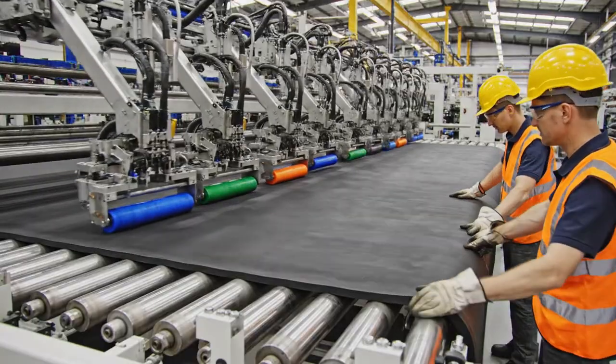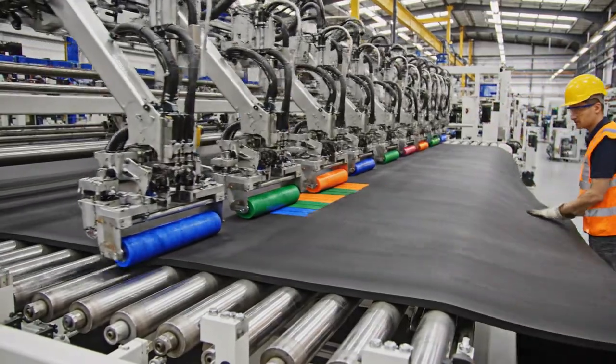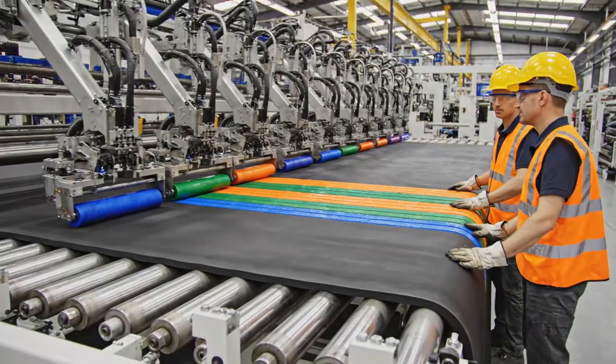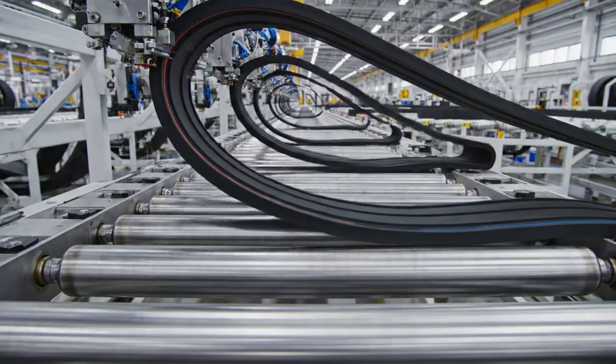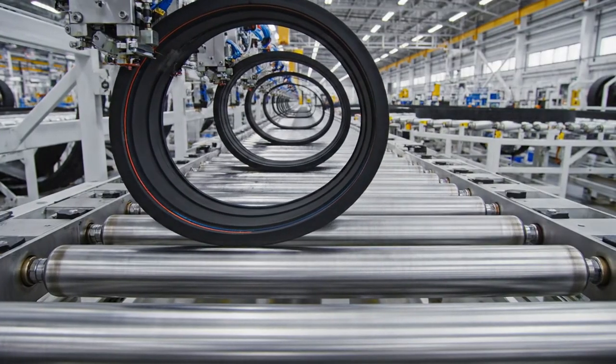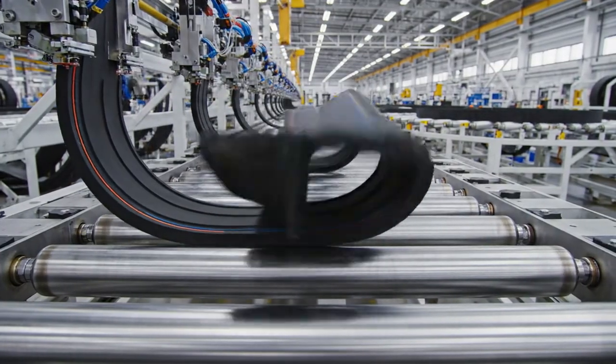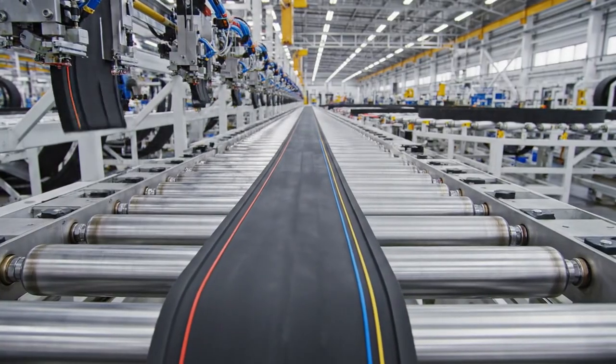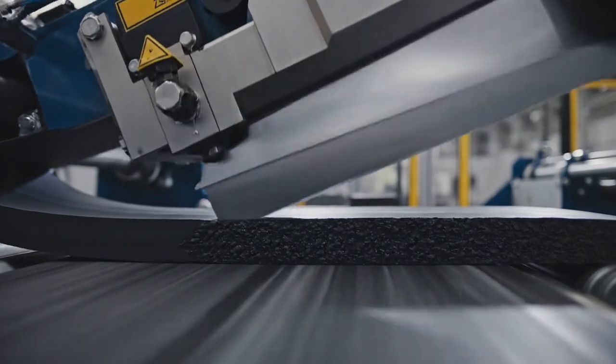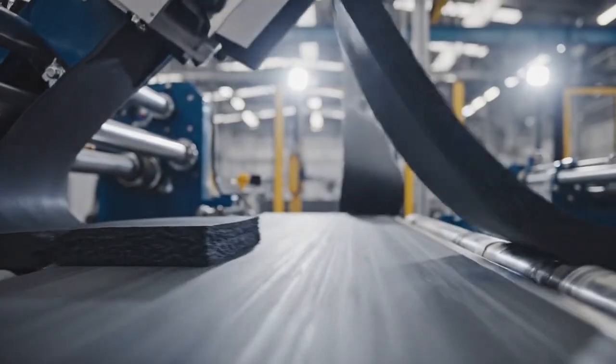Extruders shape the 3 streams of rubber, and then they enter a die that forms them into one. Many paint rollers apply different colored stripes. This way, the factory can identify the different ingredients during processing. To avoid tension, the system creates slack in the feed. A blade then slices the tread rubber to length.